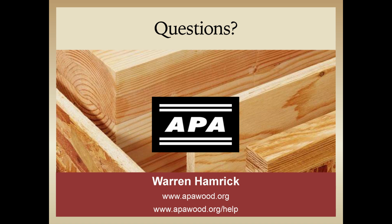Wonderful. And along those same lines, a little bit different: we've talked a lot about IRC buildings. Can these details be used in either high wind areas or on really large buildings that maybe fall outside of the IRC? They likely can, but if it falls outside of the IRC, then that's when an engineer needs to be brought in, and you're going to start looking at your shear tables and things like that. You're falling into a shear wall design at that point. So likely could be used, but consult with your designer.